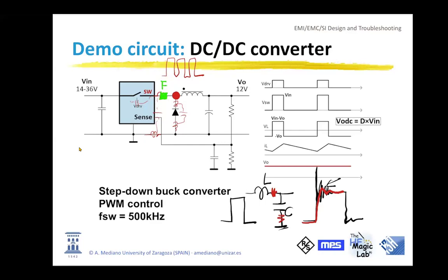So the jumper I was talking about is exactly here. This is one pin, this is another pin, and the jumper is here. When the jumper is in position, it's short-circuiting the ferrite, top to bottom. And when you saw the mountain moving left to right, right to left, when I introduced and moved the jumper, the idea is that in these pins I have some kind of parasitic inductance, no?